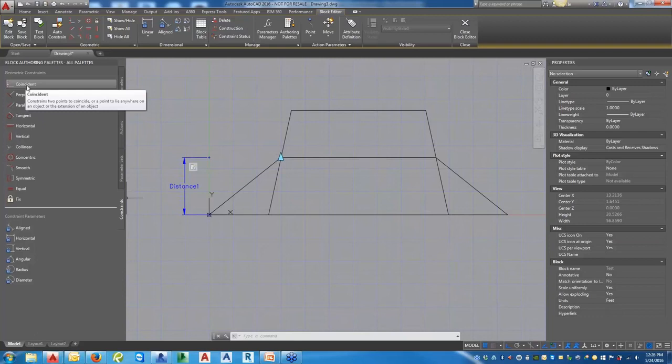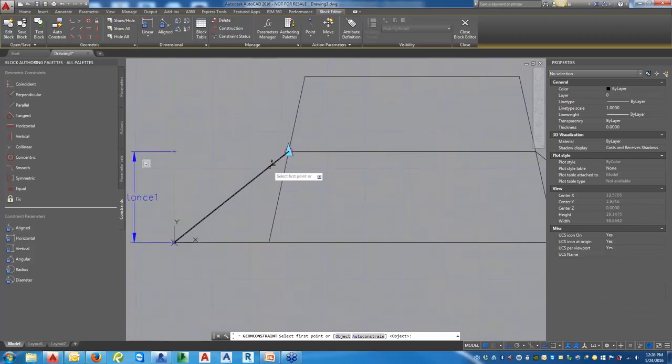So let me go ahead and select this here. First off, I want to look at this line segment and see that little red dot, that node. That's where I'm going to start my first point. And if I wanted to, I could constrain it somewhere to the line right here. Now, I don't necessarily have to use these nodes. Right now it's giving me three options: one for the midpoint and one each for the endpoints.